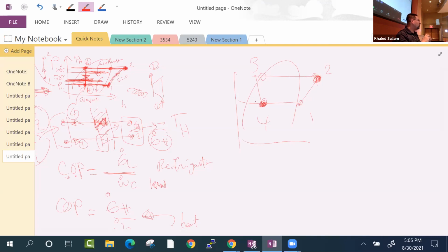Okay. So very smartly, they have the compressor and the throttling device with a 3-way valve so that you can switch the exit of the compressor and say, go outside, it's summer, or go inside, it's winter. Okay, and of course, the throttling valve will do the same. They actually have 2 throttling valves ready to be engaged, right?